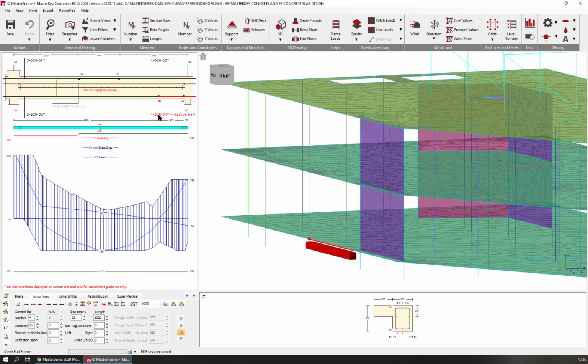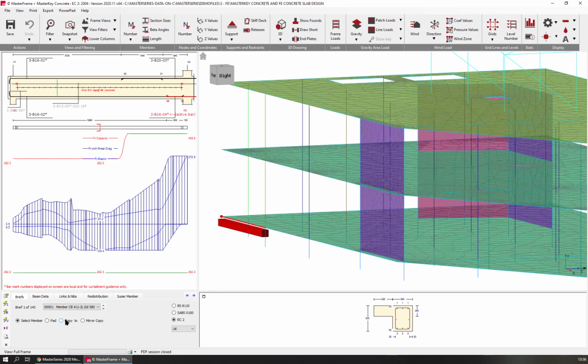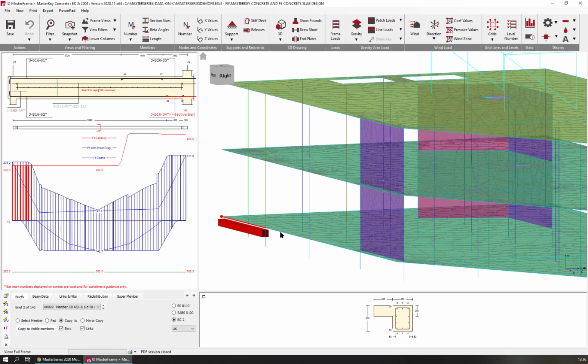So we can work with our rebar and we can play with it. We can change our diameters, and we can even take the rebar from one configuration. So that's way over to the top. I believe 20s is going to be good enough. 2 20s, maybe 3 20s, and just go for a 3 bar arrangement. Pull that down and make that 3 16s. Normally you try and keep them all the same when you're doing this 2 bar lap, and I can then say let's copy that to the next span and see what happens.